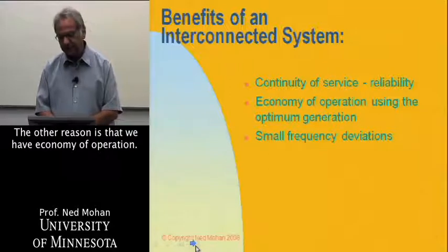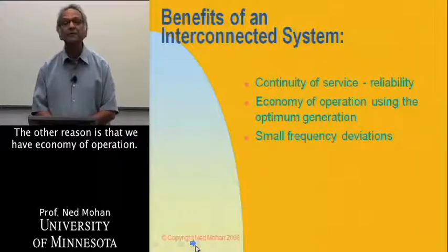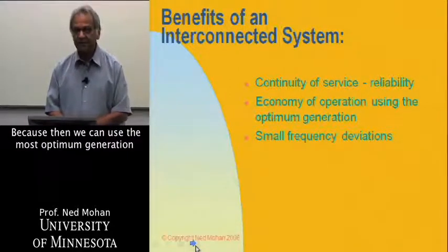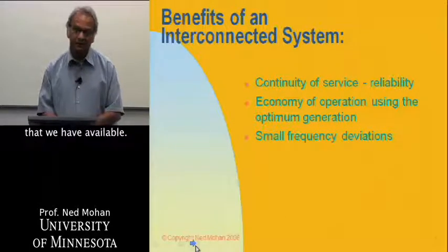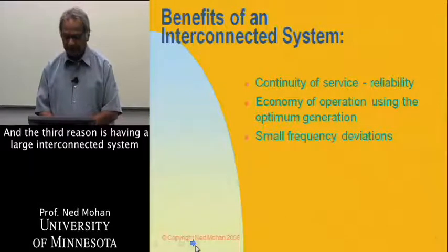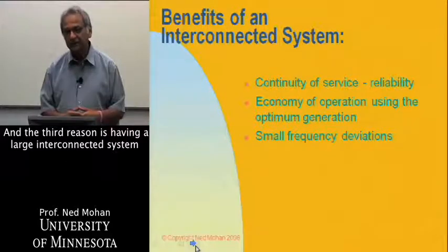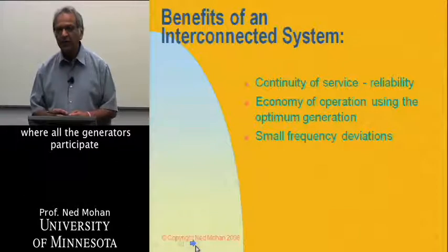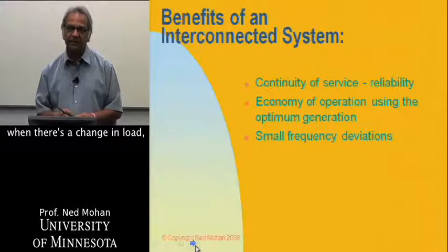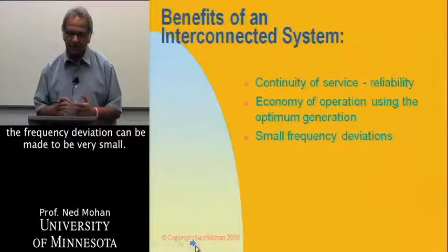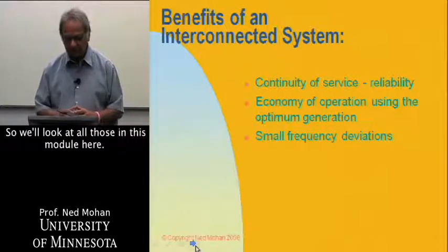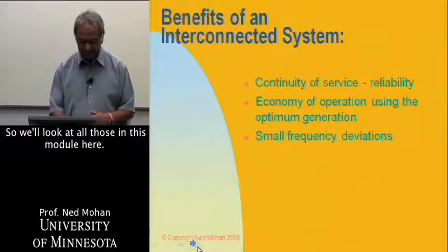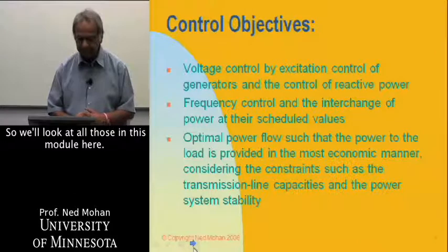The other reason is that we have economy of operation, because then we can use the most optimum generation that we have available. And the third reason is that having a large interconnected system, where all the generators participate when there is a change in load, the frequency deviation can be made very small. So we'll look at all those in this module.